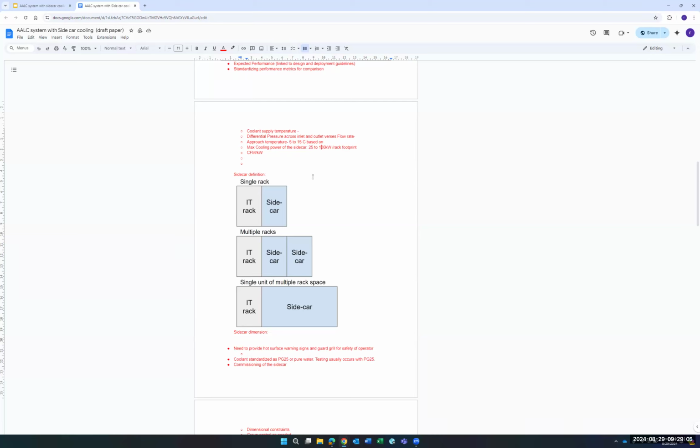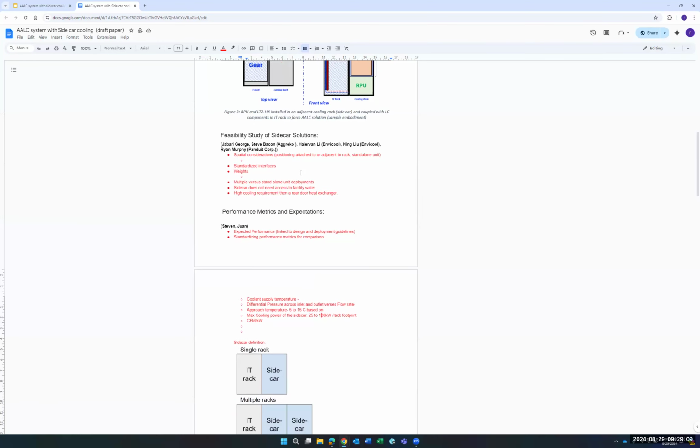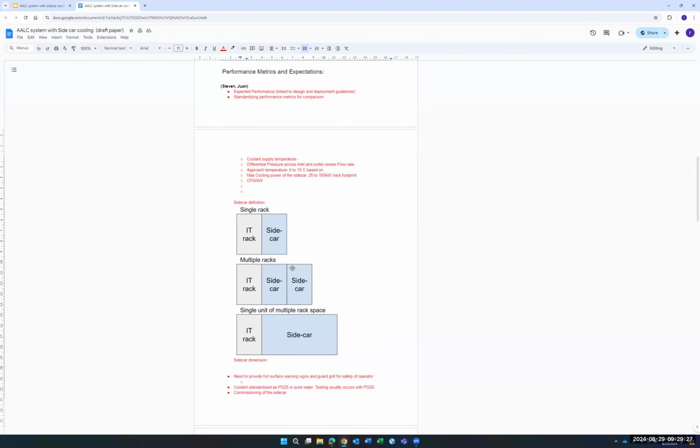But I would put those numbers down by your boxes there showing single racks, so you could say that the cooling range is 25 to 100 kilowatts or 25 to 70 or something for a single wide, with an approach temperature varying from 5 to 10 or 10 to 15 or something like that on there. So somebody could look at that and say that's way more than...